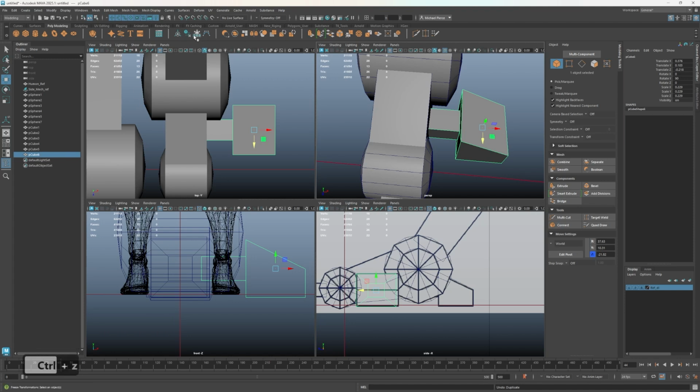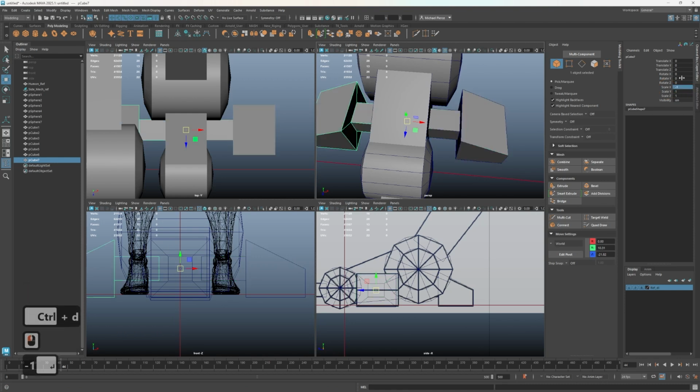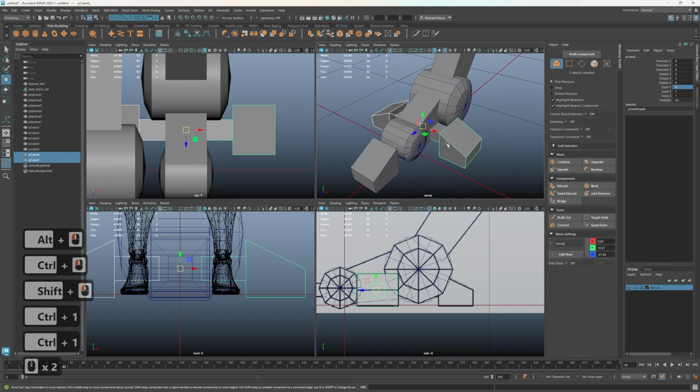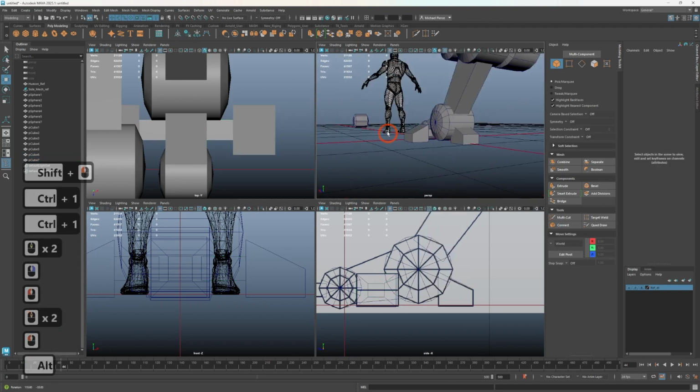Actually, here, I'm going to freeze the transform. So freezing a transform will reset the transforms of the object in its current position, right? I'm also going to tap D and hold X to move my pivot point to the center for this guy. Because now I can Control D to duplicate it, and then just -1 it on the X. Oop. I didn't duplicate it. Control D. Sure I hit that, but that's all right. That time we did. Control 1 just to double check. Perfect. So we've now got that there.